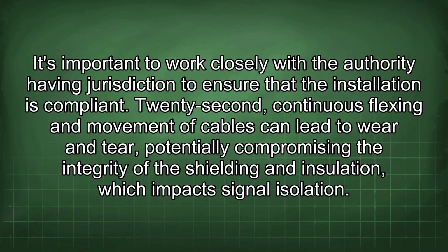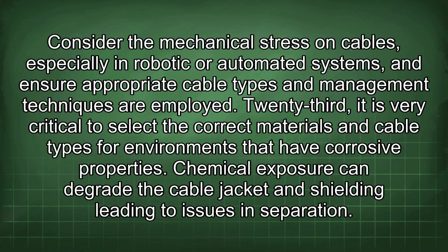22nd, continuous flexing and movement of cables can lead to wear and tear, potentially compromising the integrity of the shielding and insulation, which impacts signal isolation. Consider the mechanical stress on cables, especially in robotic or automated systems, and ensure appropriate cable types and management techniques are employed.